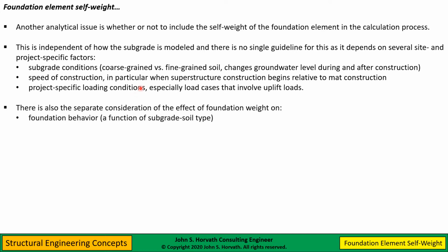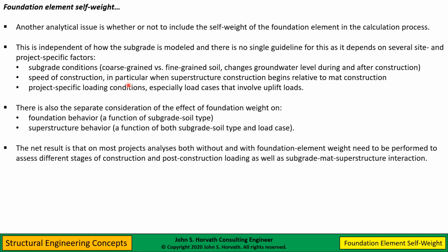There's also separate consideration when you're talking about the effect of foundation weight on the foundation behavior, that is the actual flexure and bending moments in, say, the mat itself, or the superstructure behavior, whether we're talking about the deformation of the superstructure. I found the net result is on most projects, you really wind up looking at doing multiple analyses, both without and with foundation element weight.